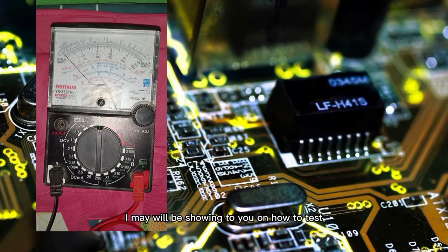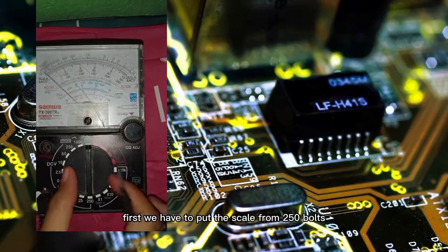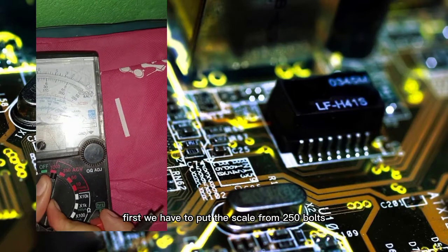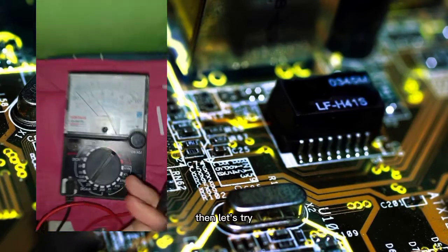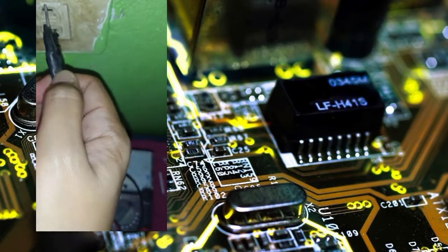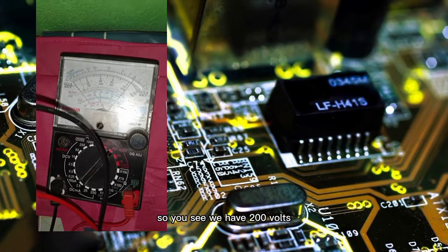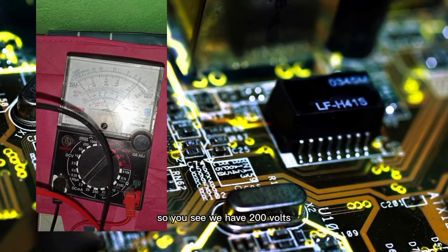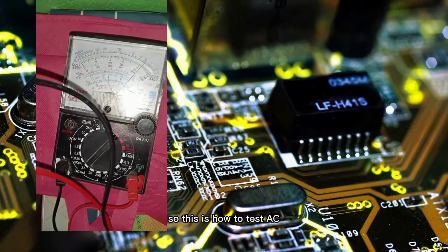I will be showing to you on how to test an AC voltage. First, we have to put the scale at 250 volts. Then, let's try. So, you see, we have 200 volts. So, this is how to test AC.